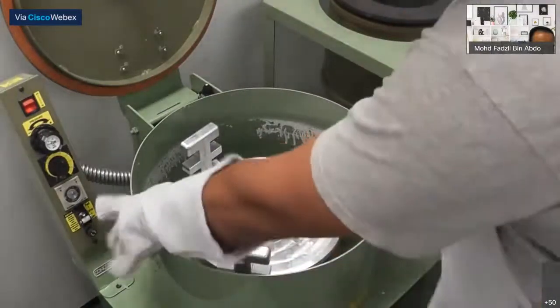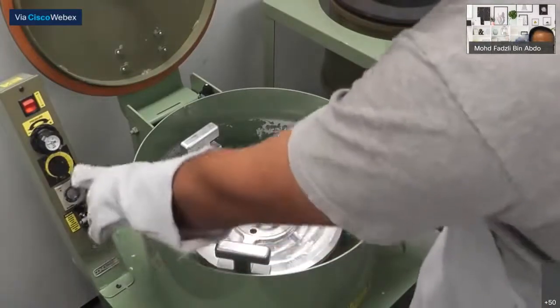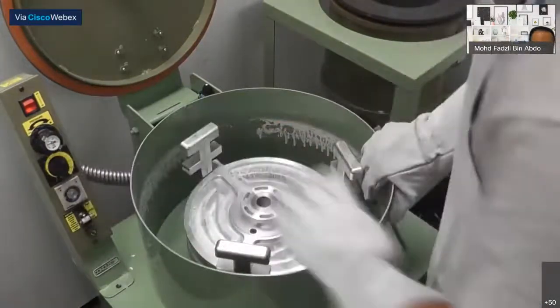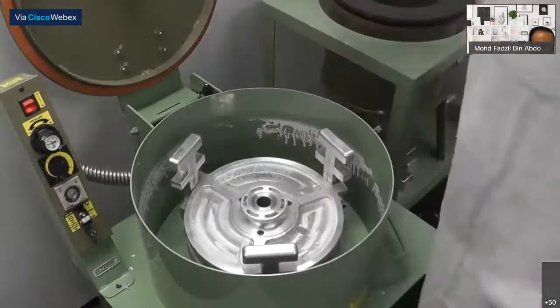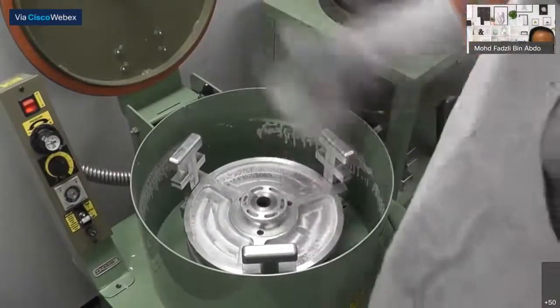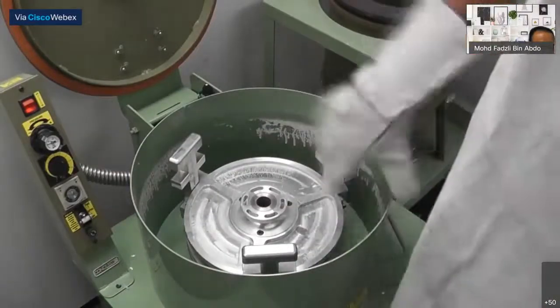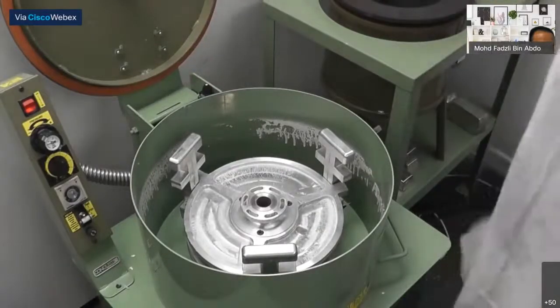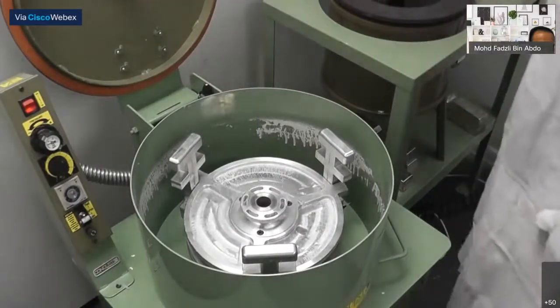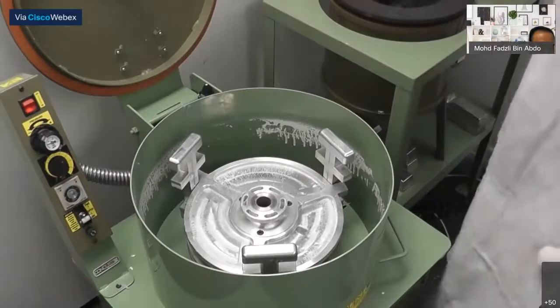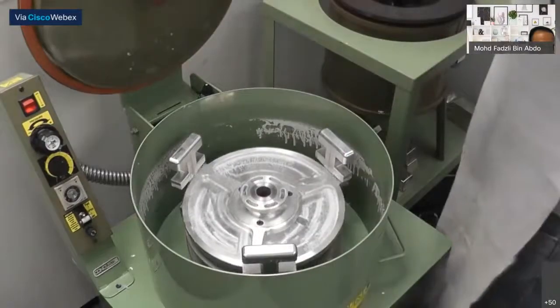So this is set, as I might have mentioned before, to spin for half a minute at 600 revolutions per minute under 20 pounds of pressure. As soon as I close the lid here, this will lift up, and as soon as it's closed all the way, it'll start spinning. So we'll grab some metal over here from the furnace. We'll close this. That lifts up.